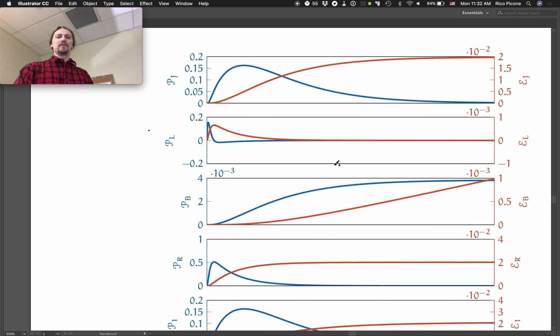Now, on the electrical side, we also have an energy storage element, a T-type, the inductor. What we see with the inductor is an early spike in power flow into it. That's when you first apply this voltage to the circuit. You see this big spike. Remember, we saw the spike in voltage across the inductor. We see this spike in the power flowing into the inductor, followed by a long period of negative power flow, it's hard to see from the graph, that slowly releases the energy from the inductor, not into heat, but back into the circuit.